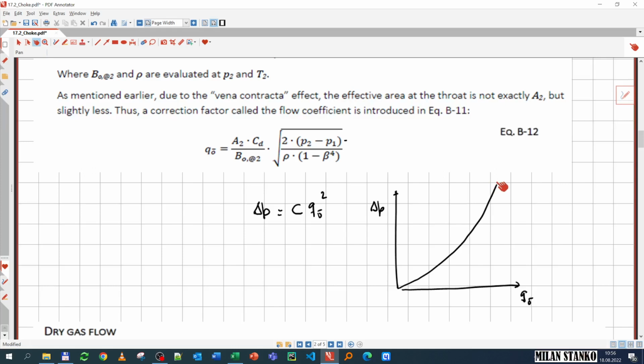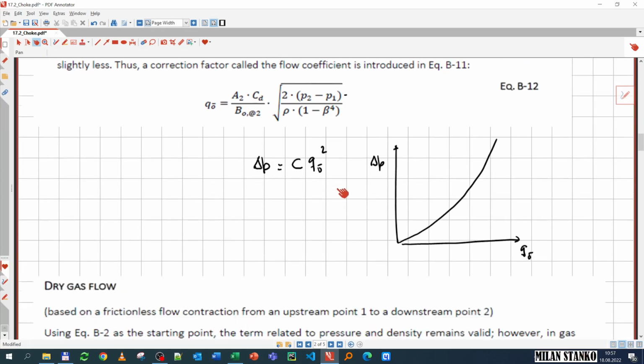But essentially for liquid, the speed of sound in the fluid is actually very high. So you will really need a very high delta P for that to occur to achieve critical flow. So in many cases, simply having this relationship and using it for the subcritical regime, not worrying about the critical, is usually a good approximation.